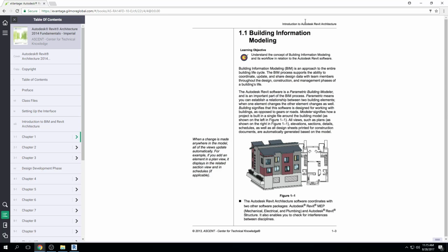Great, right? A lot of coordination, a lot of going back and forth. What's different about BIM is that I have this one central model where all of these different views of the model are contained. And I say views because when I want a floor plan of my model, I look at the floor plan view, right? When I want the elevation from my model, I look at the elevation view, okay? So instead of having all these different files, in here, I look at a view of the floor plan. I look at a view of the elevation, okay?